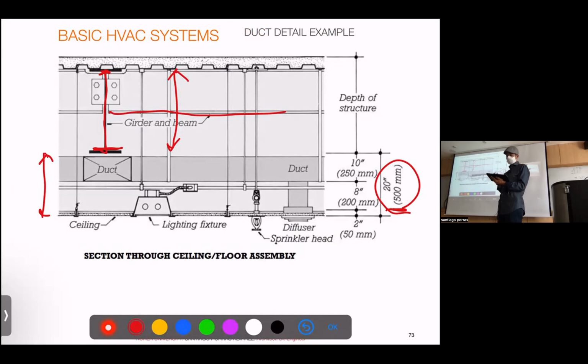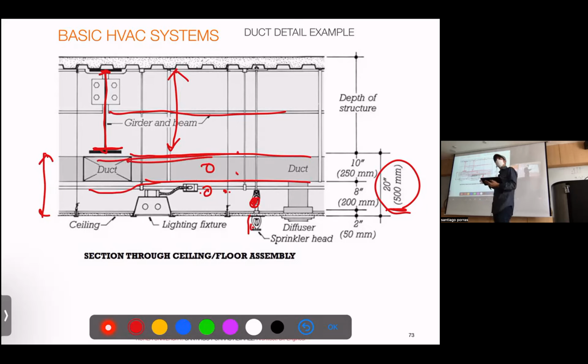The gold standard is to have ventilation, electricity, and water in the lower part. So any kind of leak will not affect electricity, right? And the ducts go first because they are the ones needing more space. If people put electricity and water, they will need to meet a lot of vents and so on, and it's not very efficient. That means the construction has to be very organized.